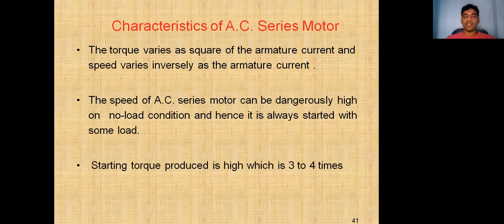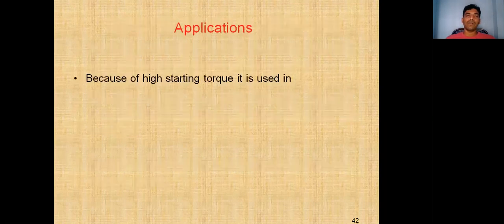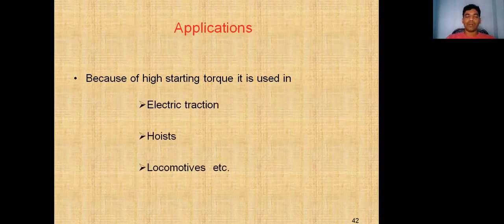Starting torque produced is high, which is 3 to 4 times the full load torque. Coming to the applications, because of high starting torque, it is used in electric traction, hoists, locomotives, etc.